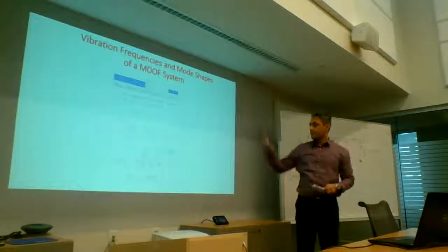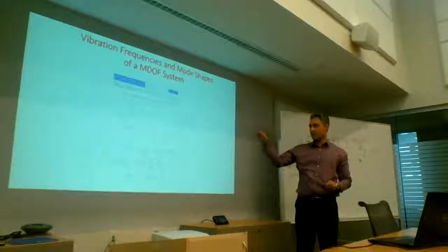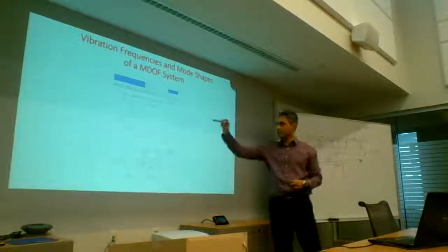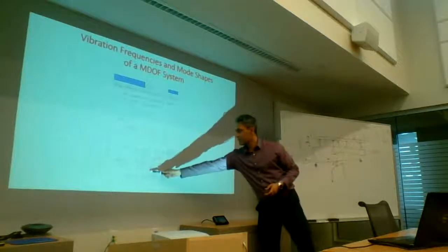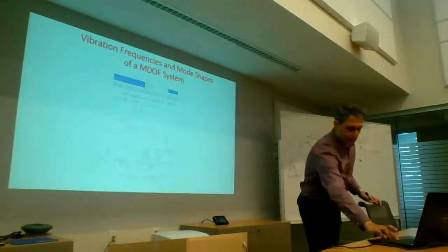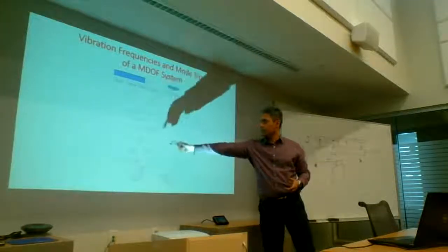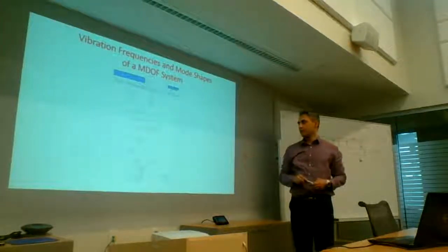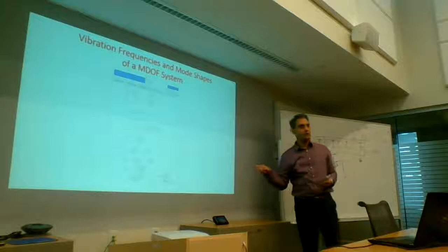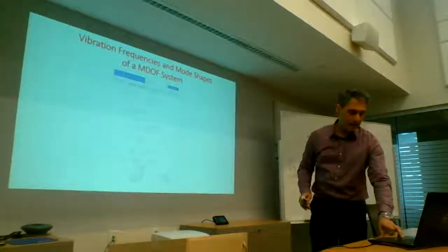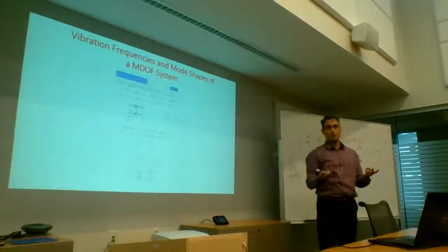And now again, this is just going through that K minus omega n squared M determinant equal to 0. Sorry, I've been saying absolute value, but that's the determinant. When you work through that, I call this quantity A, just to simplify it, my life becomes easier. I come up with an A, which then has two values, A1 and A2. When I use A1, I get one frequency. When I use A2, I get another frequency. That matches the fact that this is a 2 degree of freedom system, and it should have 2 natural frequencies.